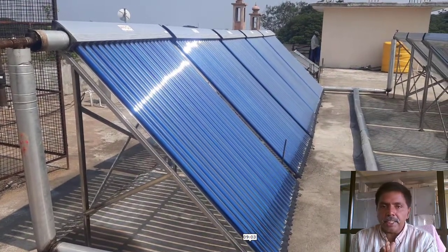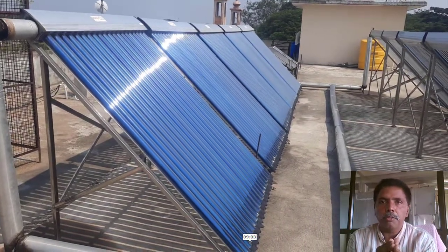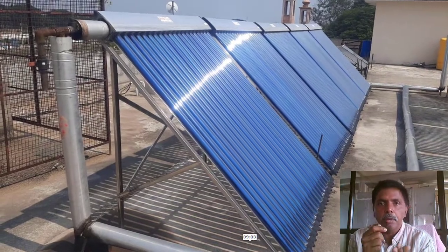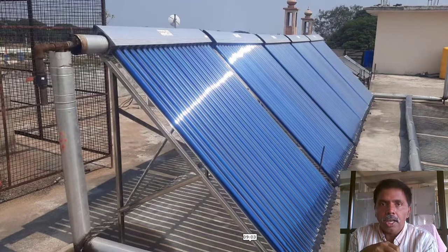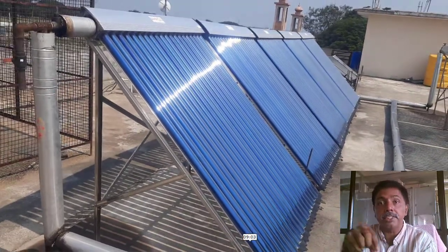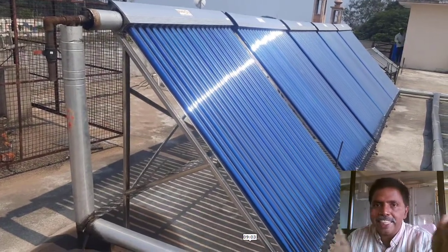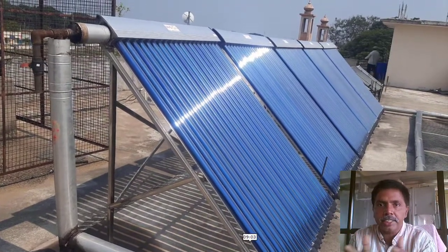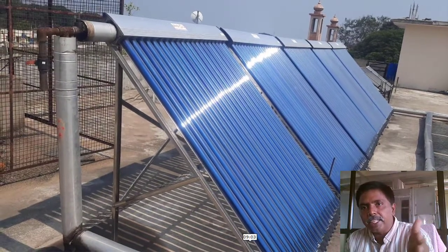Why? Because drying means we are removing bonded moisture and surface moisture. While removing surface moisture, we want to exchange the air. But while removing bonded moisture, through capillary action, the air relative humidity is not increasing, so the same air we can reuse. For that purpose we separated the heating and drying processes. In solar, generally heating and drying are combined, but in our solar industrial setup we separated them.